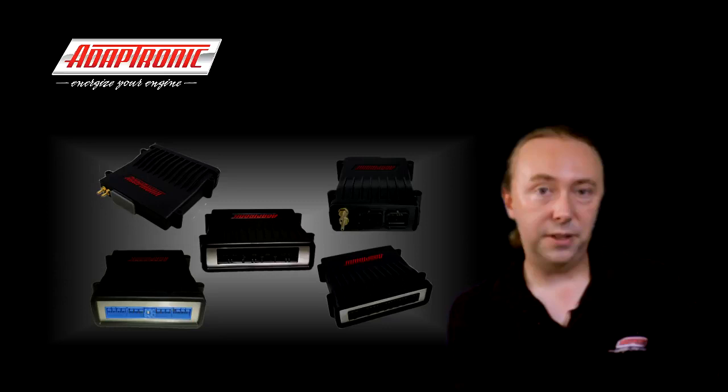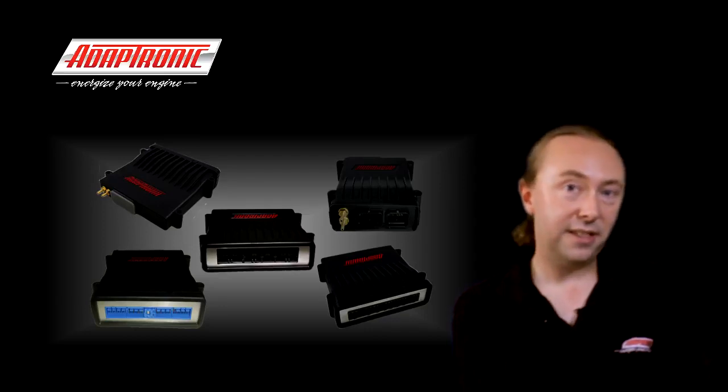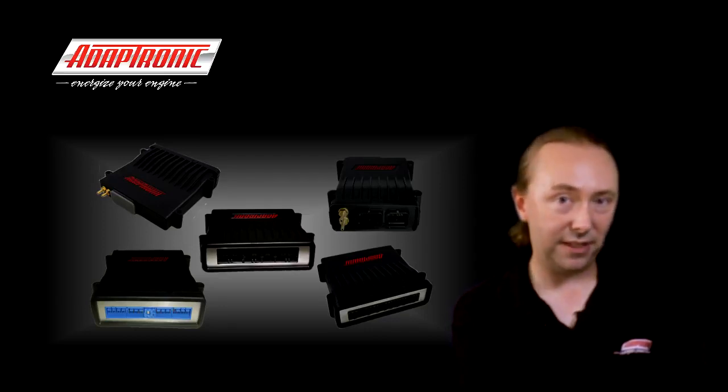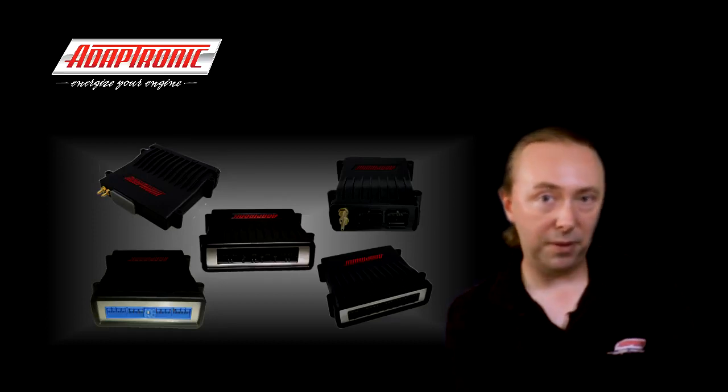Often these are called return or returnless style systems, but that's misleading because you can have a returnless that is manifold referenced if you want, and you can have a return system that doesn't have manifold reference if you want to. Generally we prefer to see manifold reference fuel systems where possible, so that the injector performance is consistent, but the ECU can handle both systems no problem.